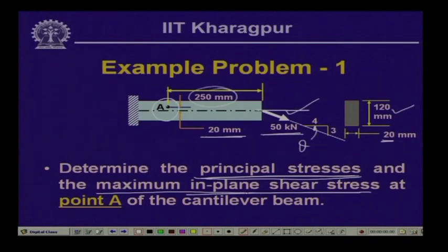shear stress. Now, this particular load, which is acting at an inclination with reference to the beam axis, at an angle of theta, can be decomposed into two directions. One is in the axial direction, another one is in the perpendicular direction. The axial force will cause an axial pull, and thereby there will be normal stress because of that, and the transverse loading, which is the component in the vertical direction, will cause a bending and a shear at this particular cross section.